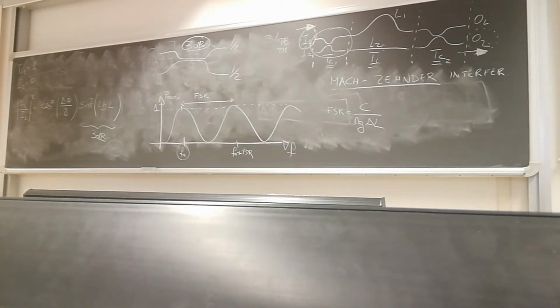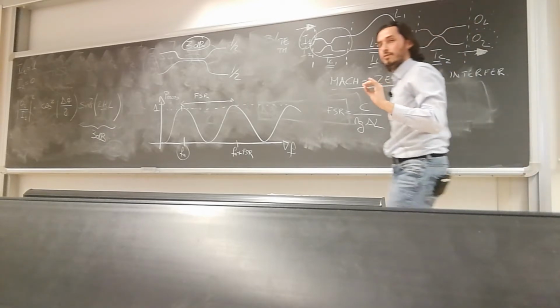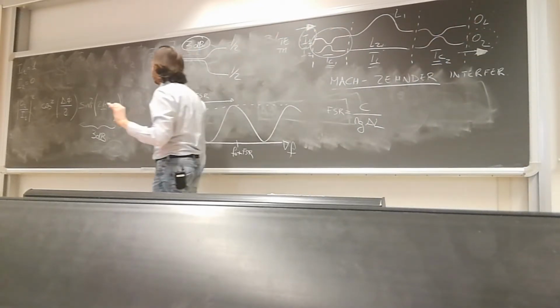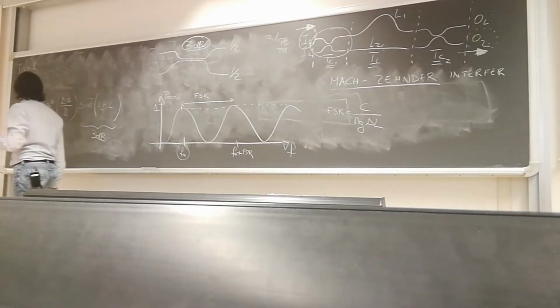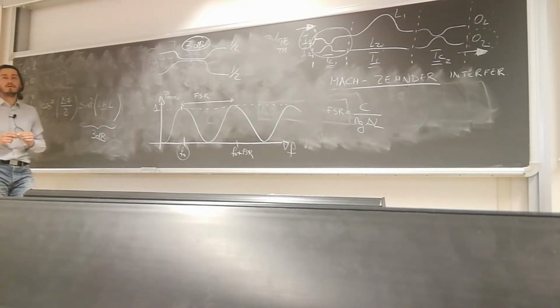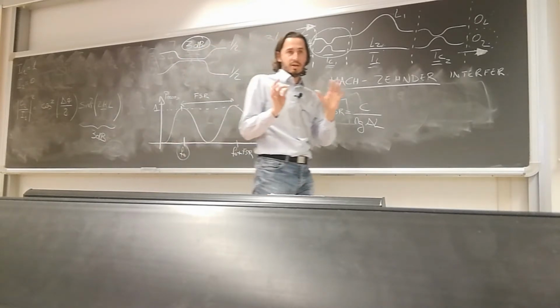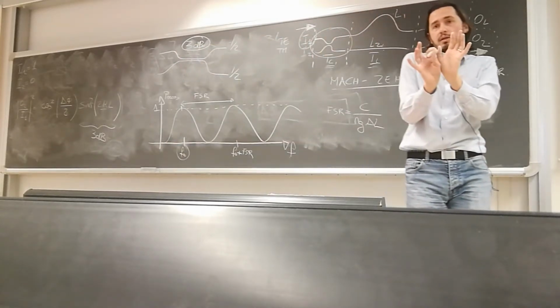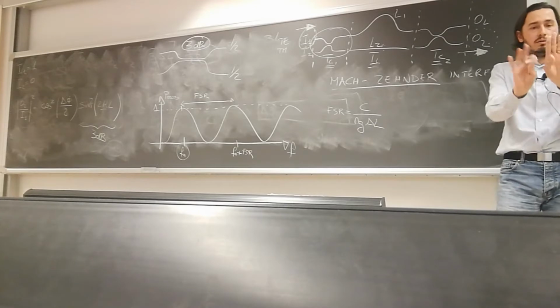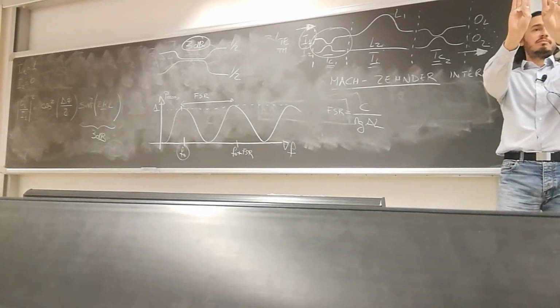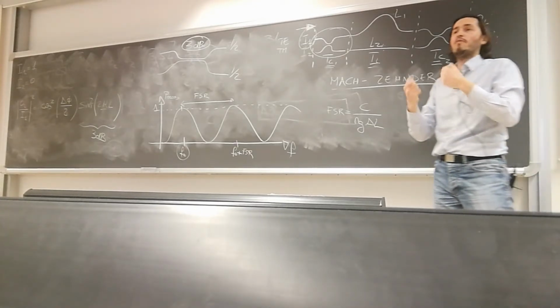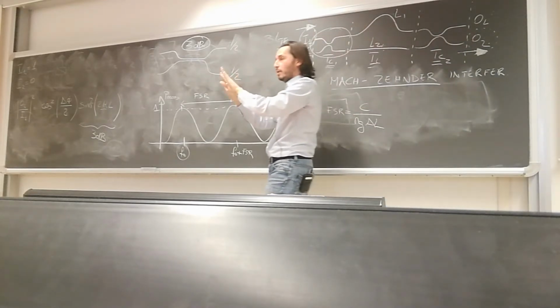It changes with the wavelength. Because we have to compare the dimensions of the directional coupler with the wavelength, maybe. The distance between the waveguides, D. K depends on the distance between the two waveguides. Okay, but the distance is frozen, is there, does not change. Okay? Yes. The waveguides are like this. Yes. I change the wavelength of my signal. Why should the coupling change?